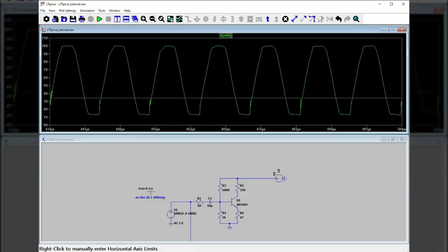The advantage of that "don't show me data until a certain time" is if suppose there's a length of time where there's a transient response that hasn't rung out yet, and it makes the data invalid at the beginning of the simulation.